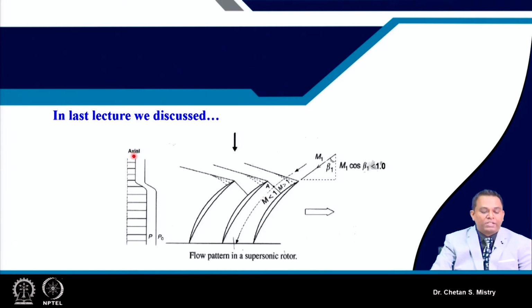Now in order to understand, this represents how my pressure and total pressure vary in the axial direction. Once it reaches the shock, we will have a sudden rise of static pressure as well as total pressure. To our requirement, we can understand we are getting a sudden rise in pressure. We are talking about a pressure rise expected more than 1.4, maybe 1.6, 1.8 or maybe 2.